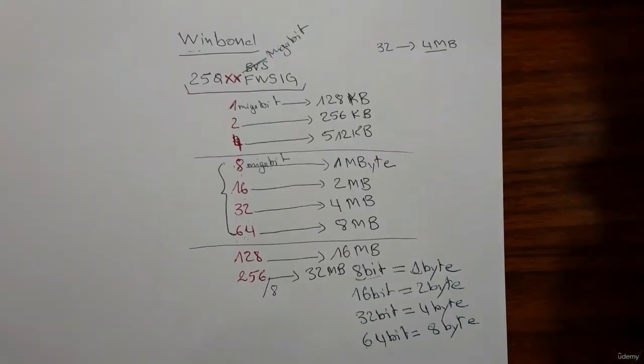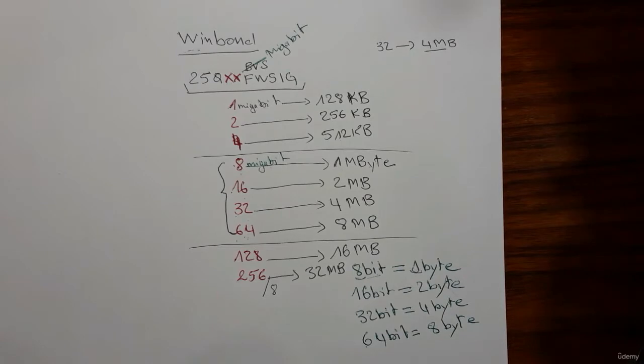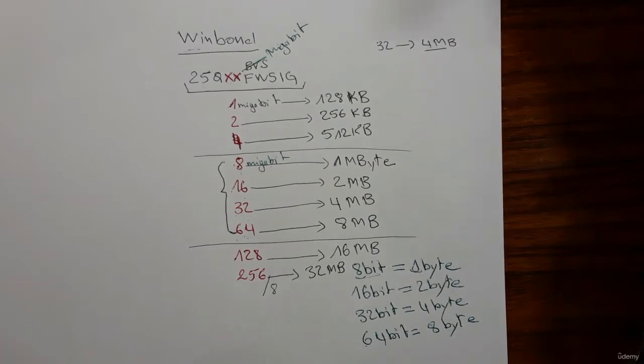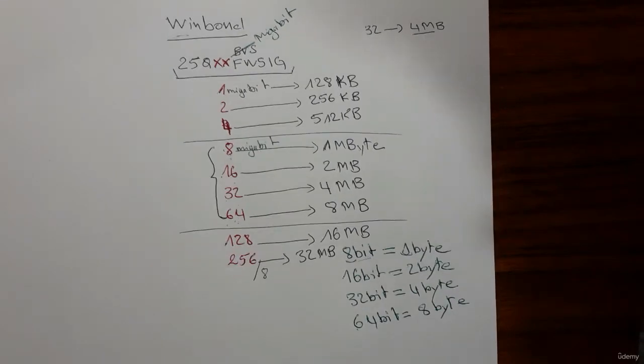Okay, so these are the main important tips that you should know about BIOS sizes, because if you want to reprogram the BIOS, you should first know its size. Why? Because when you know its size, you can compare the BIOS size with the size of the flash file that you will use to program the BIOS.